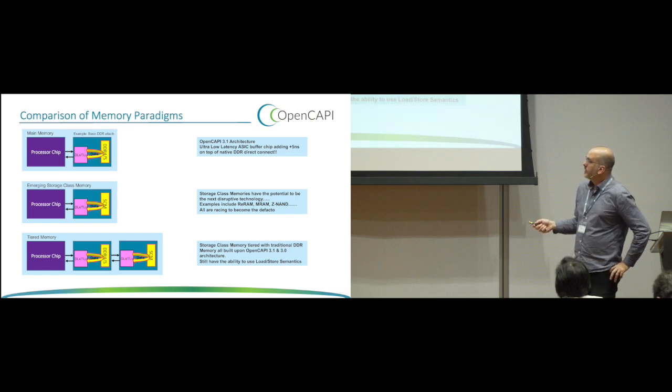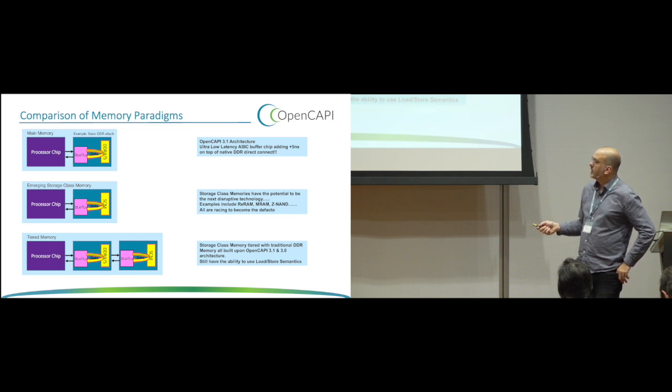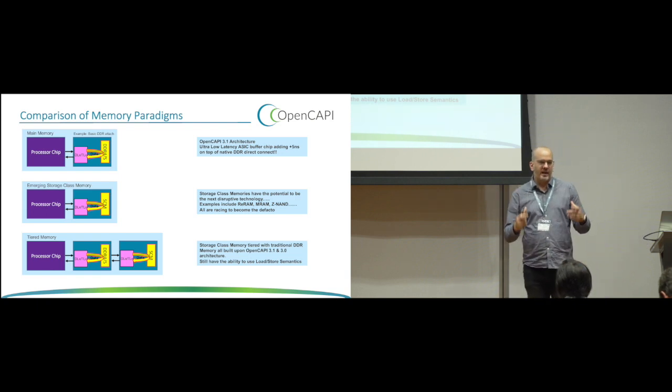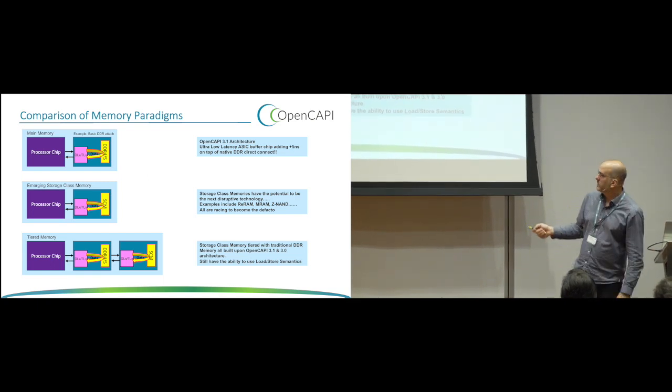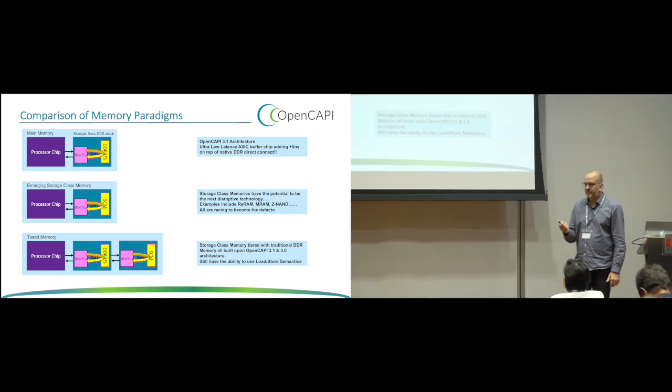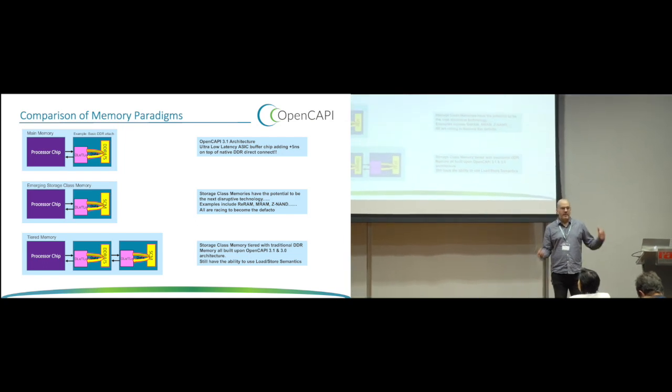Other things we could do: this is showing sort of cascaded OpenCAPI interfaces, but really the device that's probably more relevant is possibly a device that has both DDR in it and other types of memory. And this is really what Ken's thing was doing, would you say this is close enough, right? So we have DDR, which is frequently accessed, and then you have some other larger pool of memory that you use as a second level tiered memory solution.